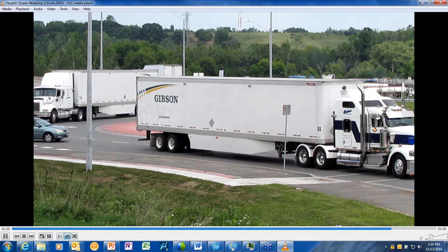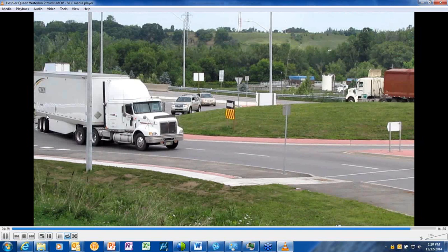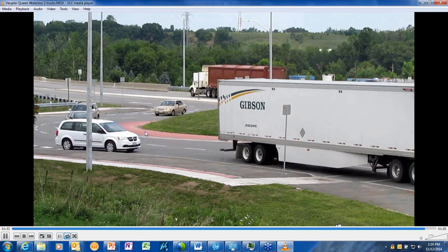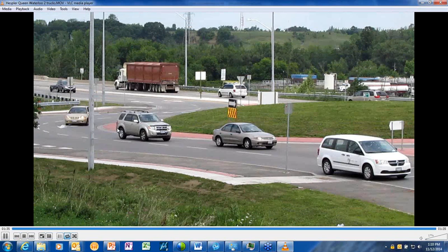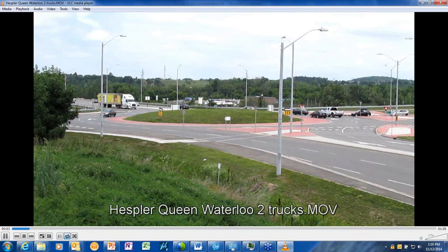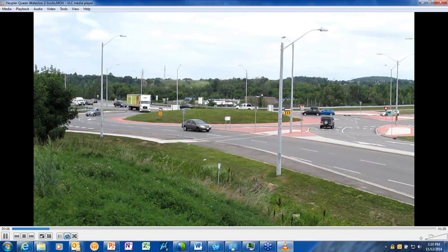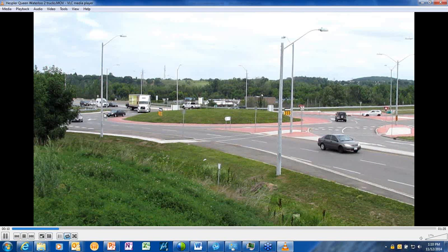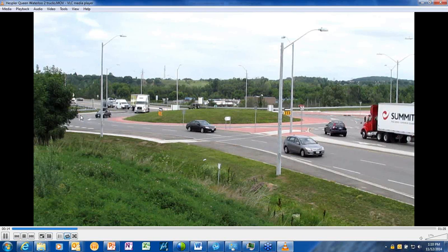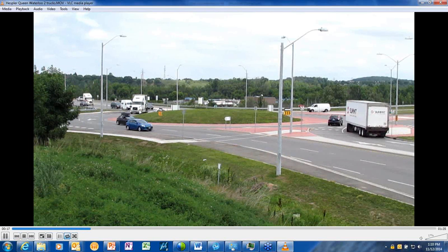And this is typical of what the driver training people tell us, is that they'll keep to the outside if they can and keep traffic on their sight side. That's their definition of traffic, being able to see traffic from the driver's seat, looking out the window. Instead of looking in a set of mirrors, they can see it positively just by glancing out the window. Once the vehicle gets turning in the roundabout, they can't see anything on the right-hand side of the cab. Not in the mirrors, and certainly not otherwise, so there's a big blind spot.